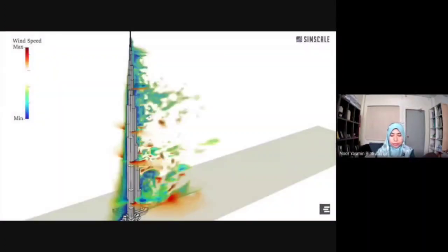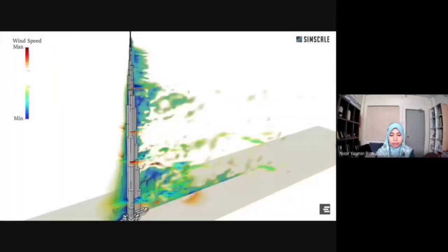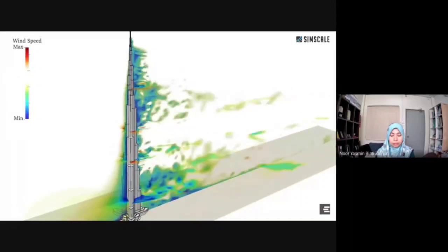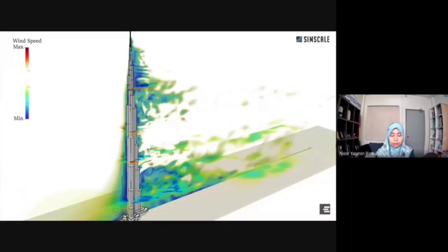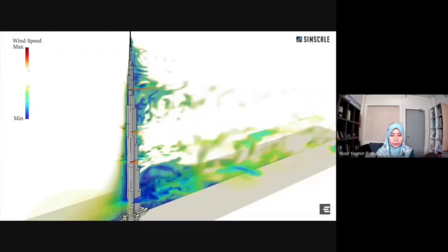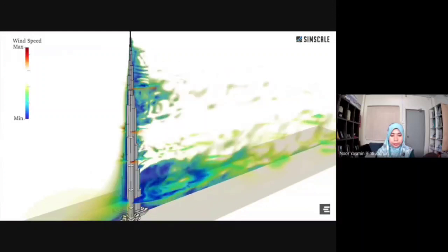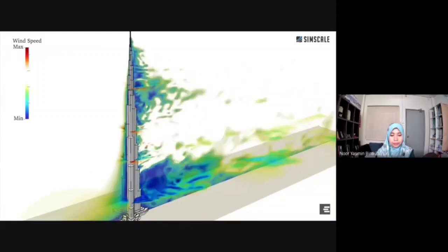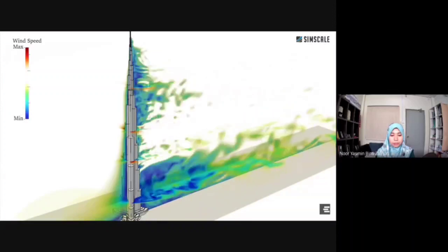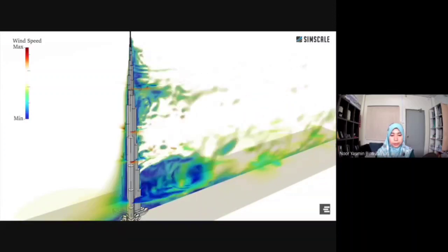Wind loads on buildings. We can see the main effects of the structure optimization in this animation that shows the flow physics at 3 different cross sections along the height. Close to the base height level, the area is largest, and so is the wake behind the structure. But the corner softening helps to avoid strong vortices.